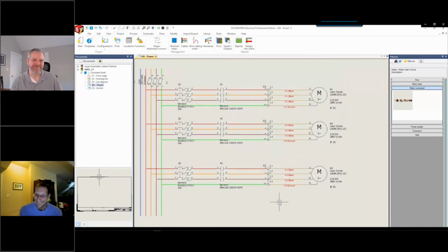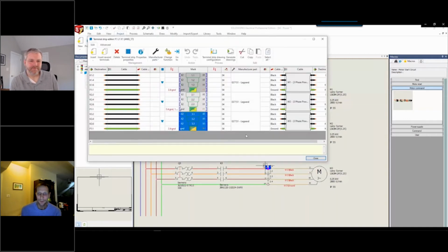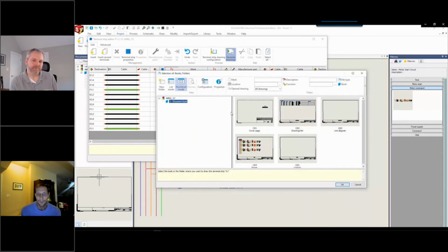Yeah. So I'm going to go ahead and reuse that data. I'm just dragging and dropping it into the open space and placing it. You'll see everything gets indexed up real nice. It's really not a worry, all of our relays. Now this is a really neat thing. Since I have a multi-level terminal block, I wanted to show that ground wires coming into 3 places. So let's go ahead and bridge them together. So we only got to run 1 wire, and then we'll jump over to those others. So a real quick way to do that.